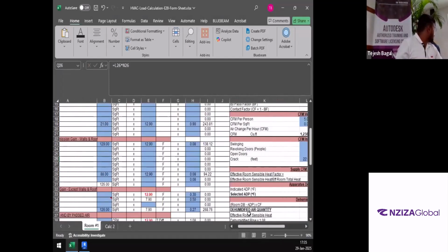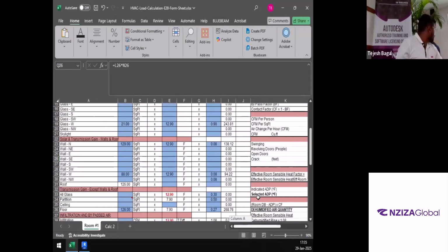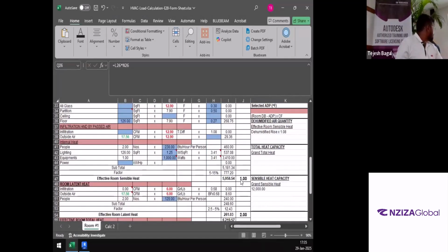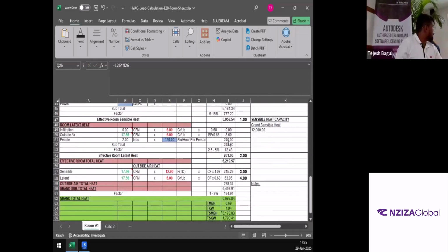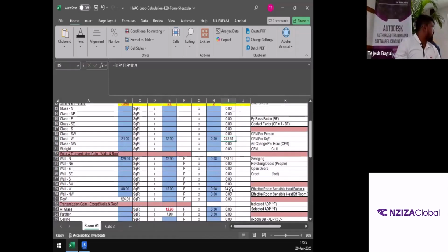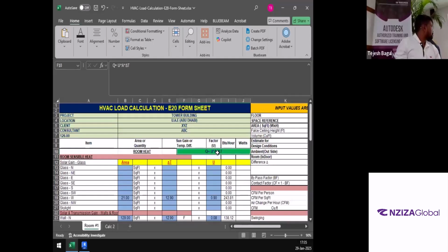All right. So now taking a look over here. So these numbers that I was mentioning yesterday, right? This is basically based on this formula over here. Okay. So over here, if you see U area into the delta T will give us this number, which is BTU per hour. Basically, indirectly, we are getting the tonnage or kilowatt, whatever we call it, for the HVAC load. Same thing happening over here. Same thing happening over here. The fundamental formula stays the same.